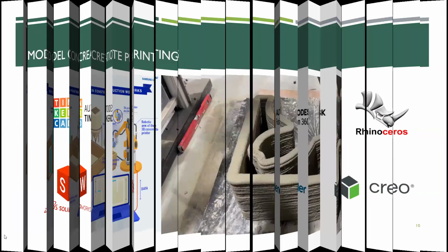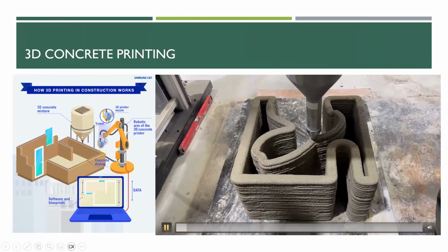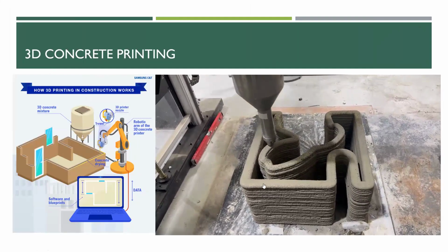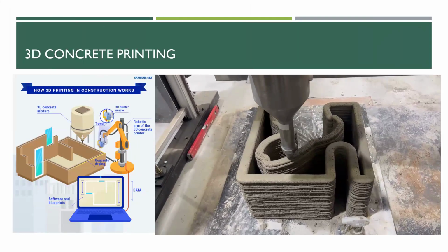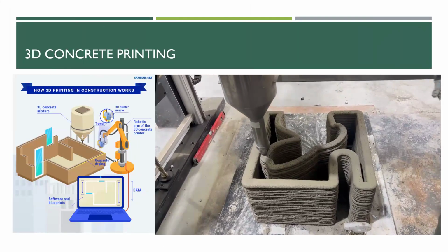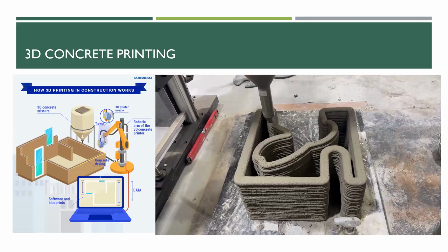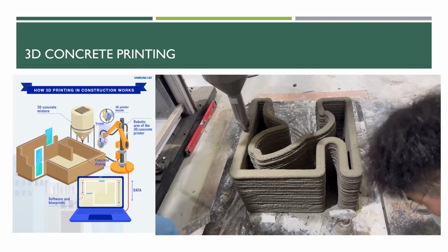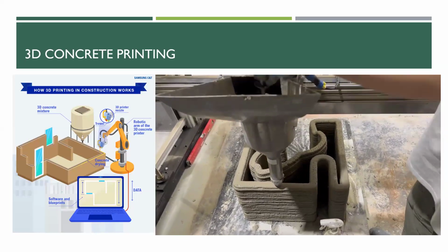Sometimes you have to convert the 3D model in the printer software which you are using. After you have input the model and you have prepared the concrete, you have to put it in the extruder, and in layer by layer construction, it can be printed. It's a small video in which we can see the layer by layer construction. It's on a gantry printer, which I'll show you in the next slides. You can see what it does depends upon the nozzle and shape. You prepare a concrete and it is printed, and it is flowable, so it can be extruded out, and it has to be hardened enough that it can support the load of the subsequent layer. So it is a layer by layer construction. I hope you can see the video and you understand the process.